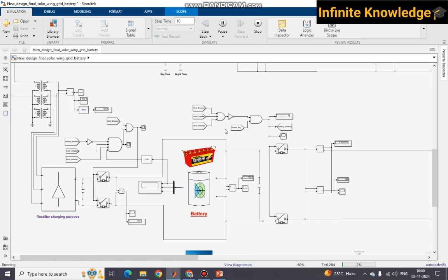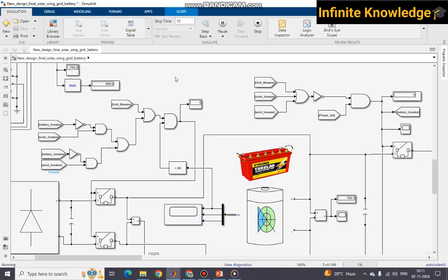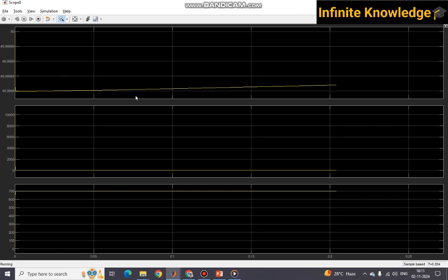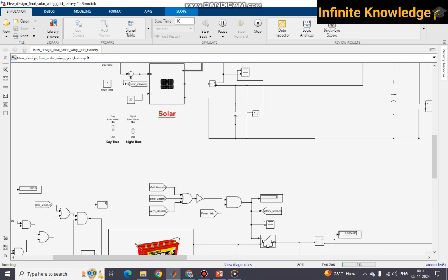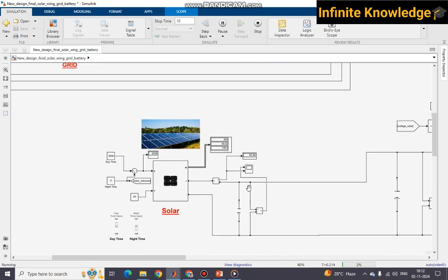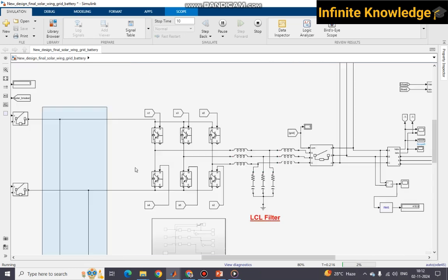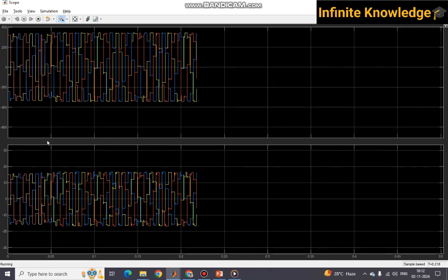You can see the breaker is closed. You can see here on the solar, the battery charging breaker is also in the closed condition. This is a one. So it clearly indicates your battery is getting charged on the solar only, and the remaining breakers, the grid, solar and grid wind, all the two breakers are in the off condition. So this is how you can develop the model specifically for solar, and solar is continuously feeding the 8 kilowatt load, and also charging your battery.